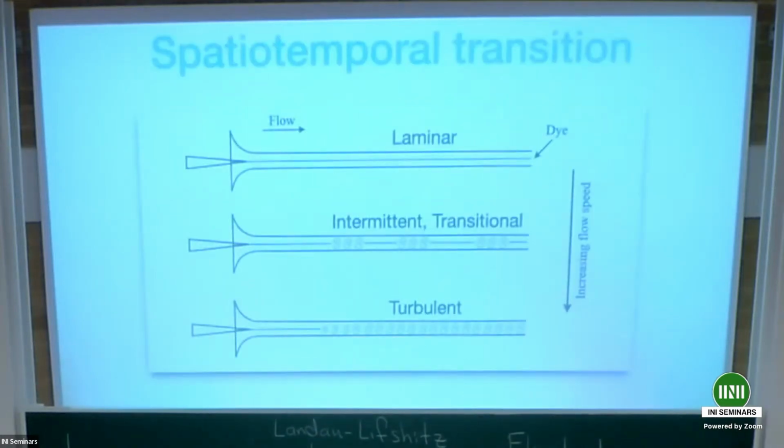Okay, so let me tell you a little bit about pipe, because it's the thing we understand best, and it's easier to explain because there's only one spatial dimension that we really worry about. And these are sketches that are modeled after what was in Reynolds' 1883 paper. This was known to Reynolds, that at low flow rates, at low Reynolds numbers, this is dye. In my world, these are extremely well-known pictures. I don't know if they're known to everybody, but these are modeled after Reynolds' pictures.